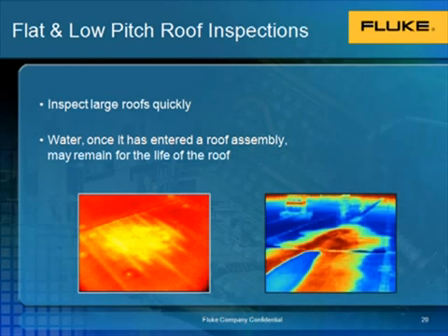Inspection of flat and low-pitch roofs can offer huge payback if inspected regularly. Nice thing about a thermal imager is that it can inspect a large roof very quickly. And once water has entered a roof assembly, it can remain within that roof for the entire life. By finding and repairing leaks early on, huge costs can be avoided. For more information on flat and low-pitch roof inspection, please visit the session dedicated to that application.